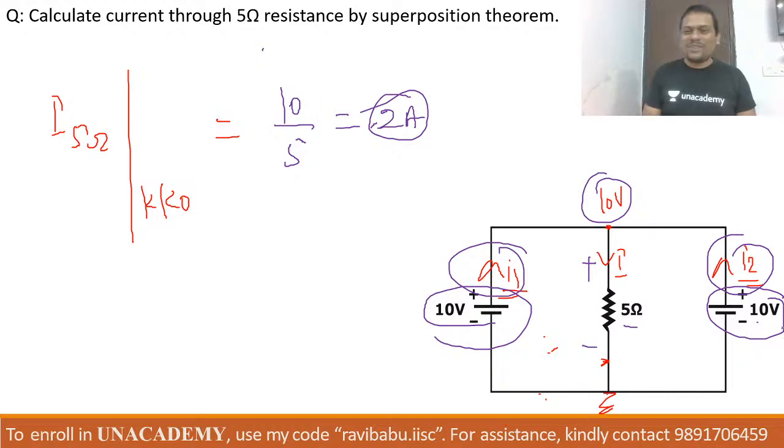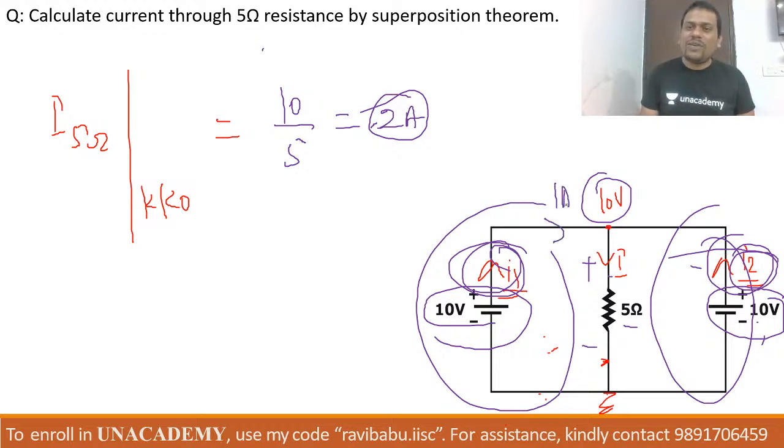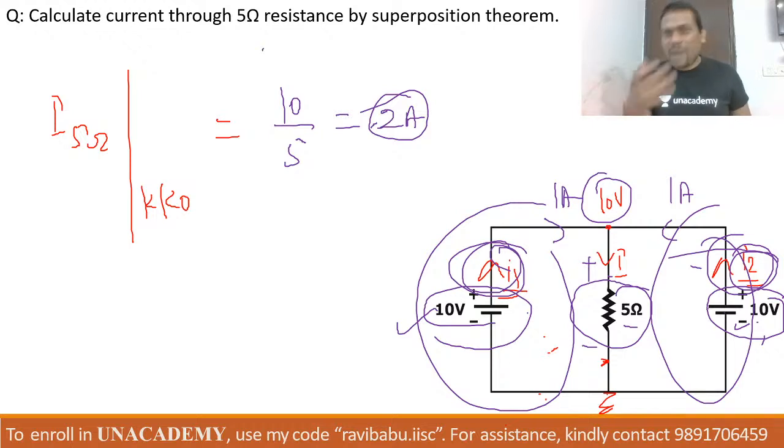Okay. So now see here, I1 and I2 are nothing but 1 ampere each to satisfy KCL. As I told you, beta, this network and that network, these two are ideal ones. So how much current will flow here? 1 ampere and 1 ampere. So the requirement of your load will be fulfilled by the 2 sources with respect to 50% and 50%. If you belong to an electrical core, then you know very well we use parallel connection of alternators and parallel connection of transformers to improve the rating of voltage and kVA. Okay, so this is the thing.